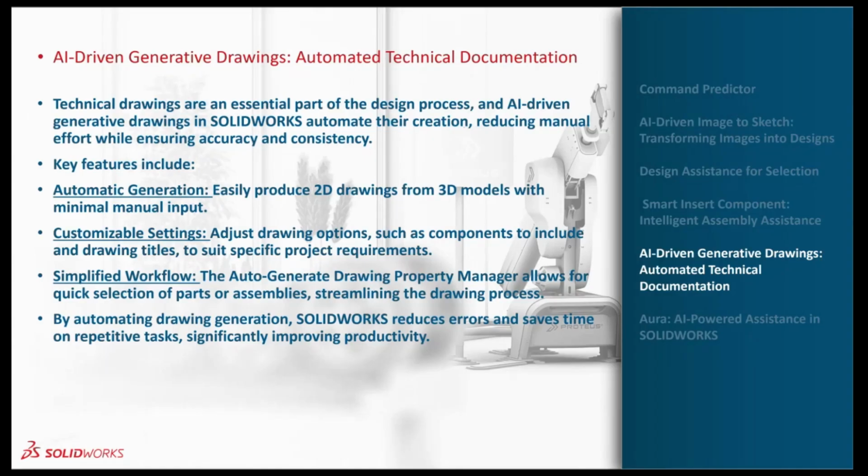It's not a complete transformation from your 2D part to, sorry, 3D part to 2D drawing. It will give you basic information like basic views: front view, top view, side view. So it will provide the basic views and section views, detail views, and any other basic views which might be required for the drawing. It will provide those views with all the dimensions: the basic dimensions, GD&T symbols, surface finish symbols, and even if it is an assembly, complete BOM information. Most of the information is completely provided by this auto-generated drawing.